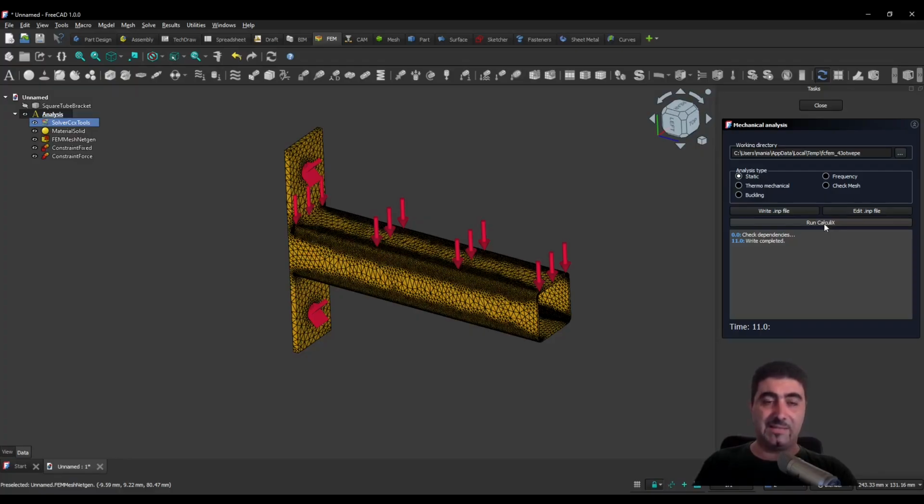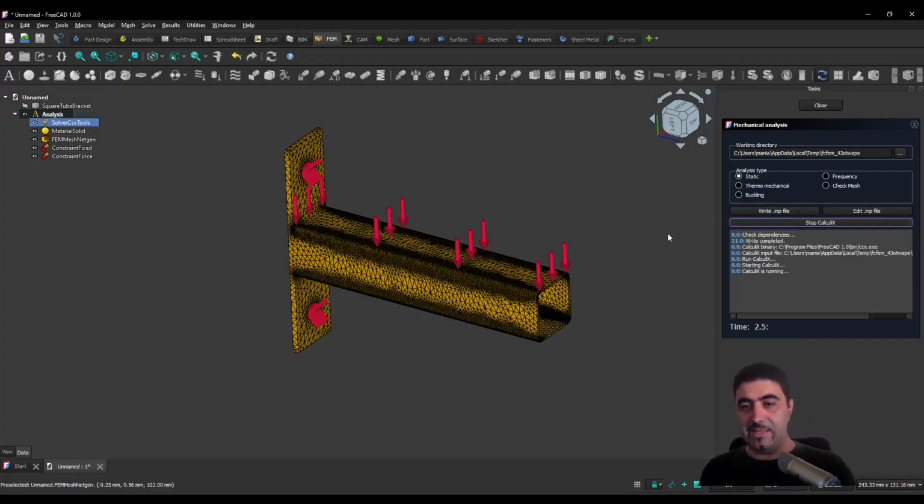Finite element analysis, you need some serious computing power. Alibre can run on a relative potato, actually, especially for parts like this, but finite element analysis, you need serious horsepower. So let's see if refining the mesh up to 330,000 nodes will make this simulation run.